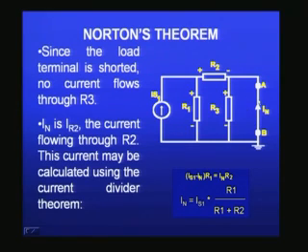Because I have shorted here, this R3 is in parallel to RL. Because I have got a short here, R3 will have no current at all. All the current will go through the 0 resistance path rather than R3, and therefore R3 is not to be considered at all. Once you remove R3, because it is not effectively in the circuit, the Norton's current source IS1 is actually dividing here into two current components. The parallel resistors divide current, that is what we see here.